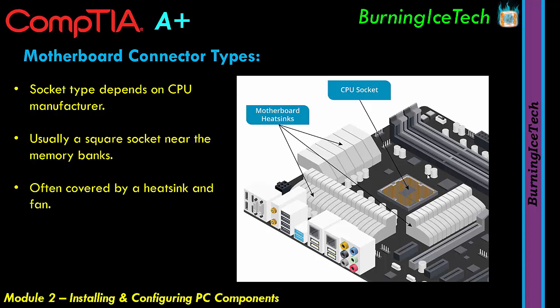The last one is on top of the CPU, there's a little arrow that points towards the missing pin as well. And sometimes the slot also has a little arrow pointing which side it needs to face. So that's going to help you guys a lot. You'll find in this picture they've got a lot of heat sinks. That's actually not the case in real life motherboards.